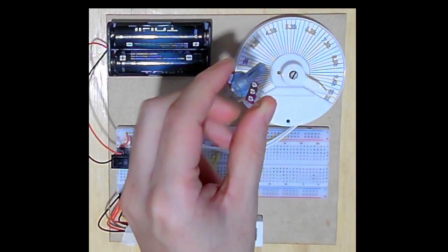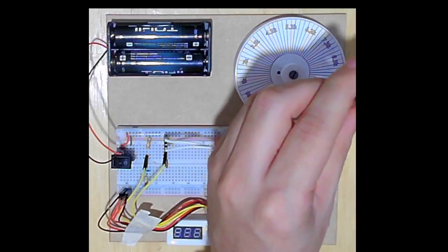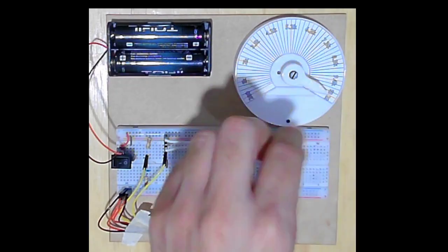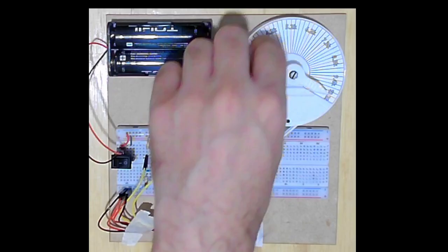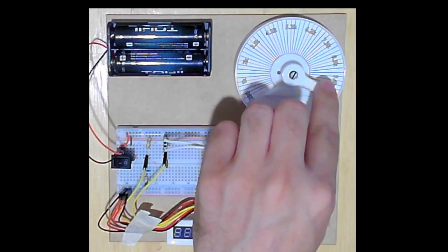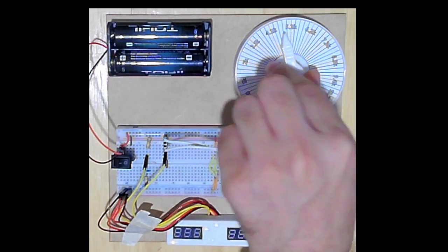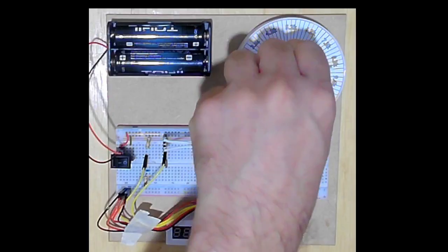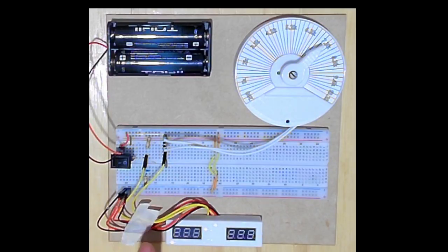So this in reality is just one potentiometer in which I am using just two pins, the middle one and one of the outer pins. And I soldered those two cables so I can connect this thing, right? And I printed this little face with values, right? So I know that in this position I have 10K, here I have 8K, 7K, 6K, 5K, 4K, whatever resistance I got, right? And the idea is that I can connect in this part the fourth resistor connected to ground, and then I can measure the voltages, right?